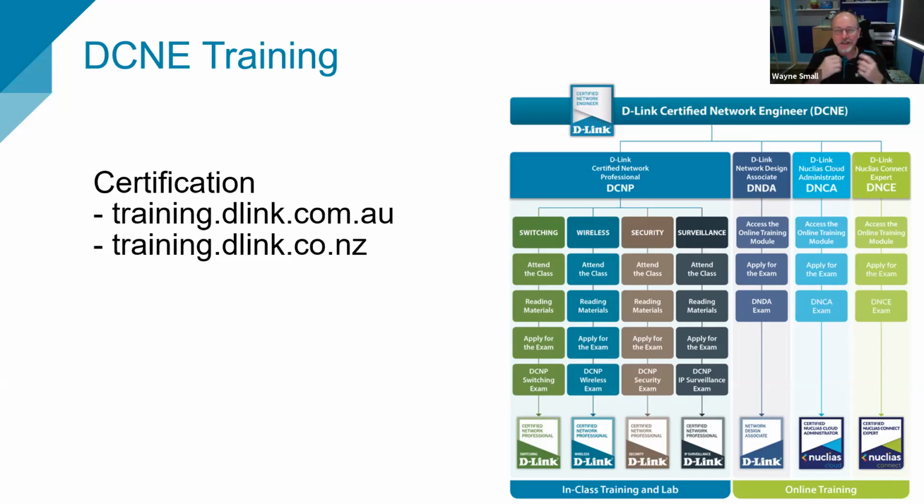So we did a cable test, and we actually found out that we had a broken pair. It was a 30-meter cable, and about 20 meters down that cable, there was a broken pair. What that meant was that it wasn't able to actually work at gigabit speeds. And of course, because we had crappy switching before, we had 100 meg hubs and switches before, you wouldn't have known. Nobody knew. So, okay, we've got a broken pair. It's a Saturday. How do we fix that?